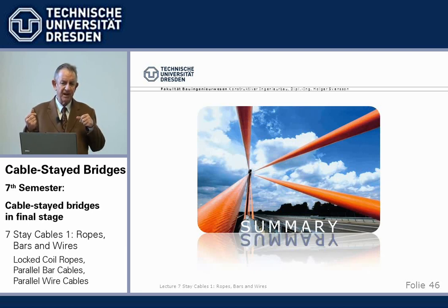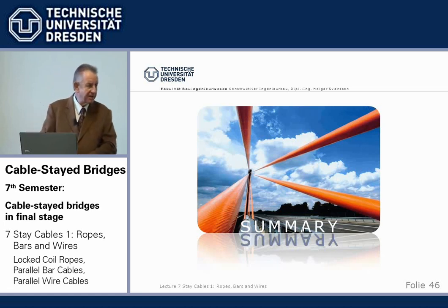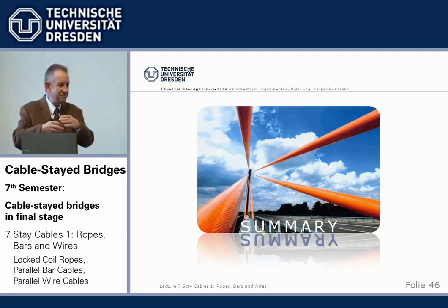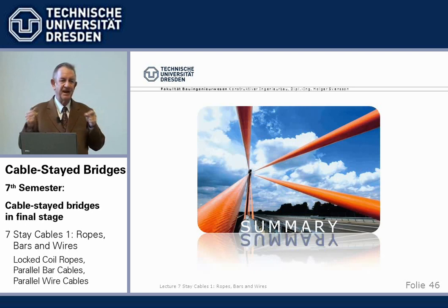On the other hand, they are comparatively thin members, say 200 millimeters, 250, not even smaller, compared with beams which are 2 meters high, and even the roadway slab is at least 20, in concrete 25 centimeters, an orthotropic deck is 300, and so on. The towers are meters by meters, so these are thin, fine members, and they have to stand up at the same time as these big, partly massive members of the bridge.